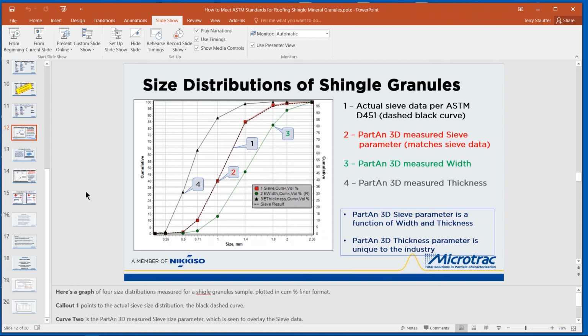Okay, so it looks like, oh no, here's another one. Have you seen a difference between samples that have been split versus unsplit using a sample splitter? Well, the general answer to that question is whenever you can, always use a splitter. Grab samples are notorious for giving unrepresentative samples. So use a splitter whenever you can.